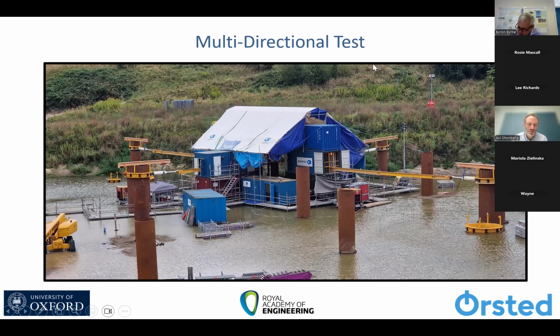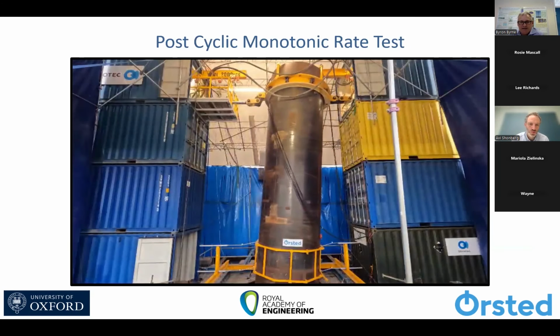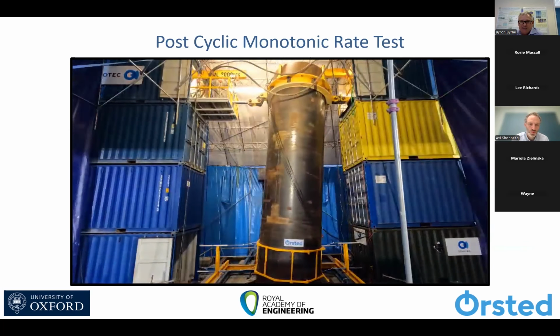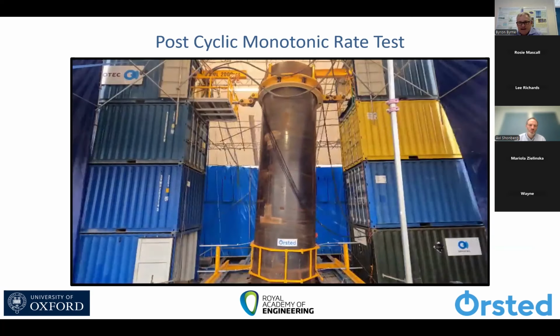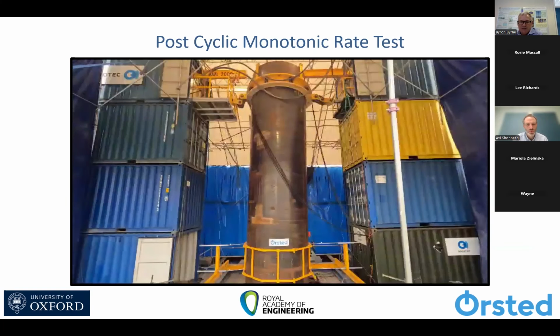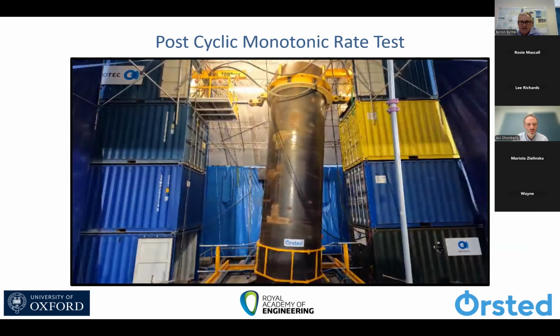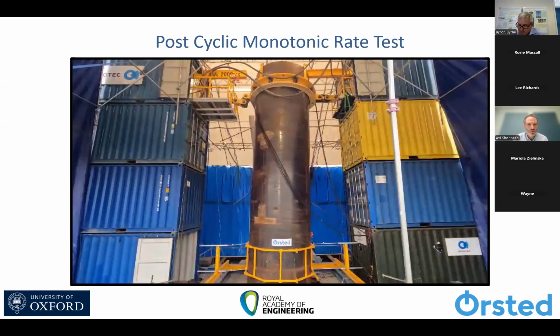And so we were able to capture, even for piles of this scale, partially drained behaviour, where rate can play a very significant part in the load displacement response of the pile. And here is just an image of a fast rate being applied at the end of the test. And so at the end of a number of the tests, we applied loads at very different loading rates to get a sense of the effective rate in this saturated dense sand at Cuxhaven.